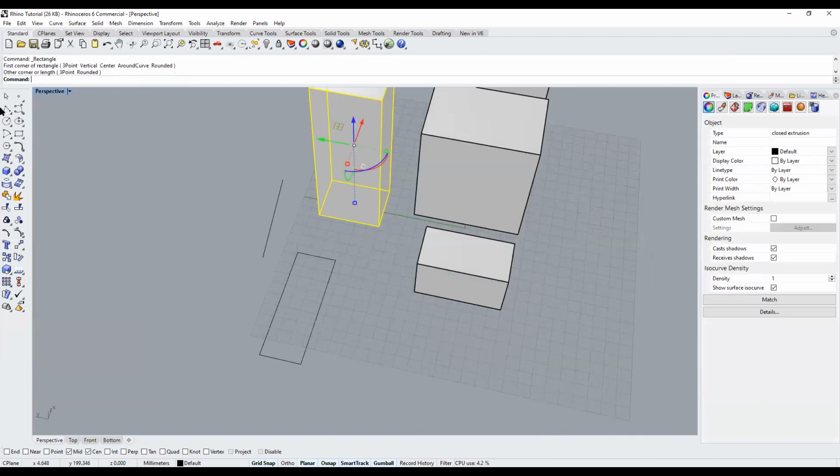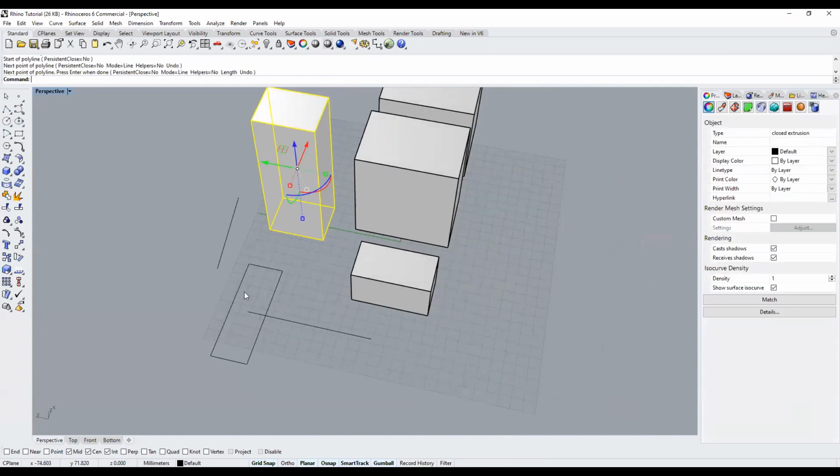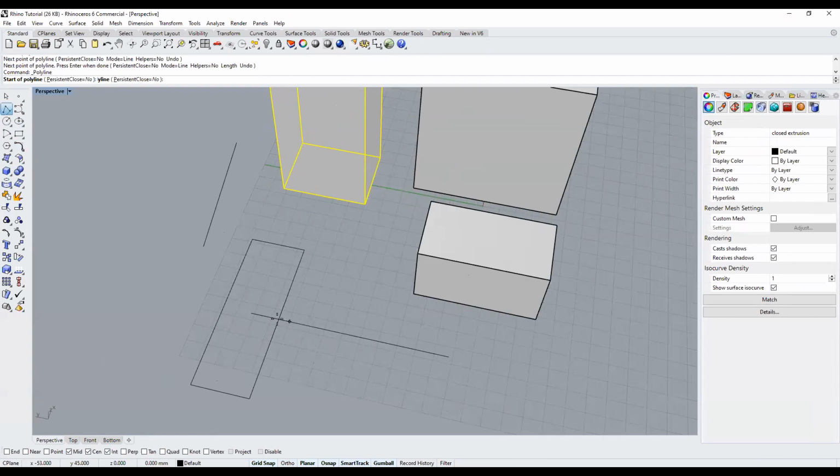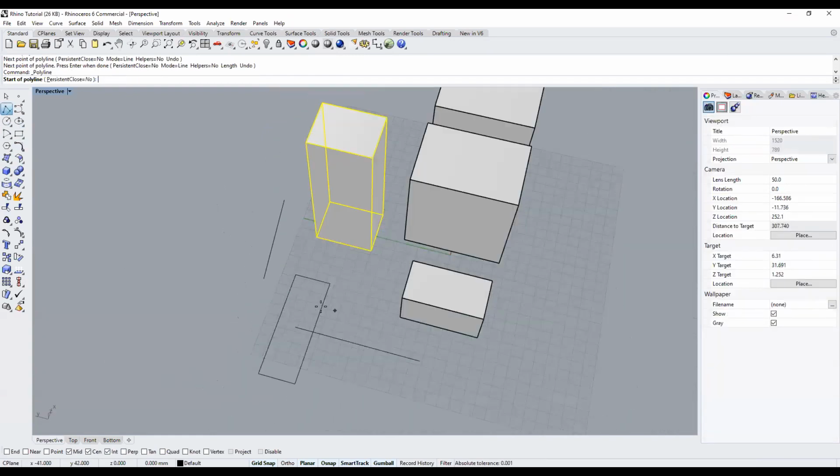This only lets you select it when you have a closed line. So if I hold it onto the boundary of this line, it would automatically snap onto the center of it. Intercept, it will snap onto the intersection between objects. This also works for poly surfaces as well as lines.